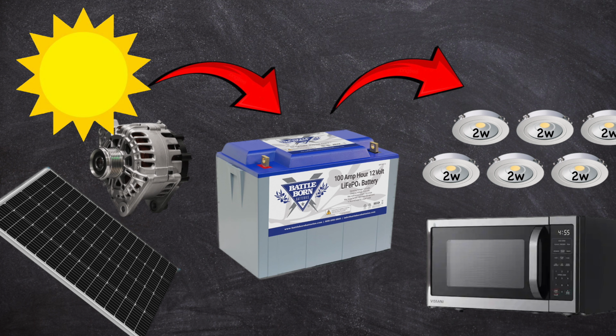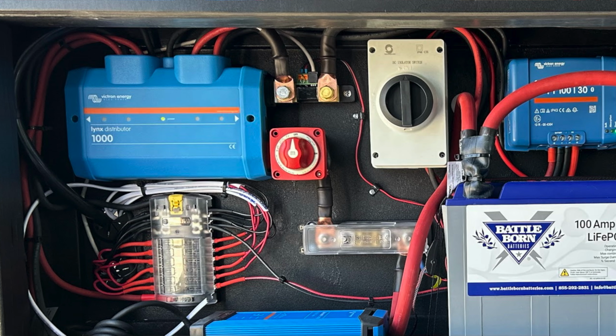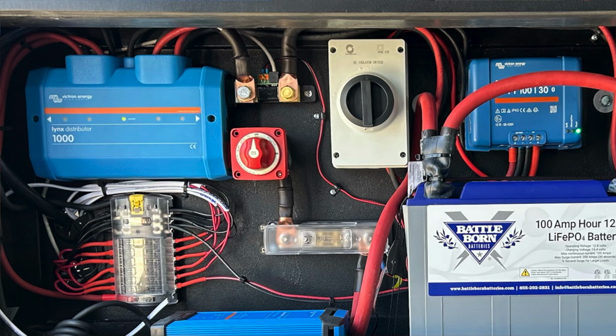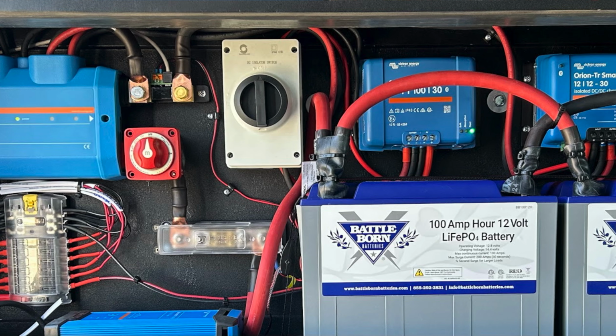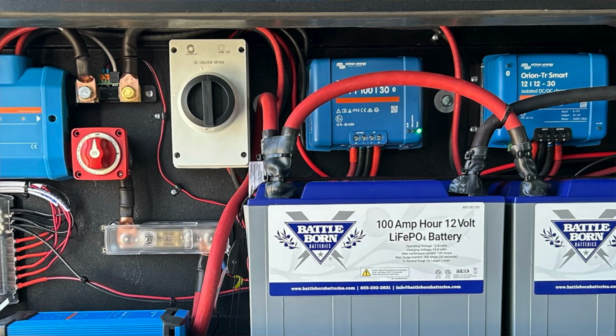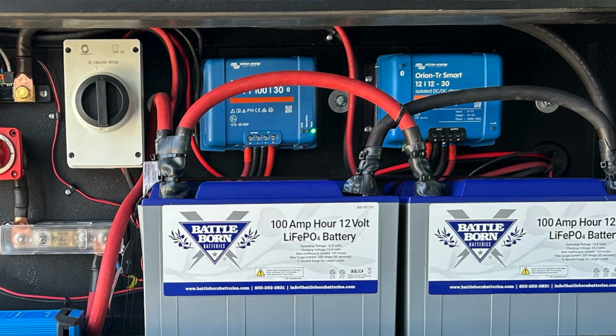Once you estimate the total amp hours you need per day, then you can size your battery bank accordingly. You simply want to have enough capacity to meet your daily needs and have a recharging system to keep up with those demands. When I was designing the power system for our van, I determined that I would need no more than 50 amp hours per day. I wanted to be able to go at least a couple of days without needing to recharge, and I didn't want to stress out about having a low battery.